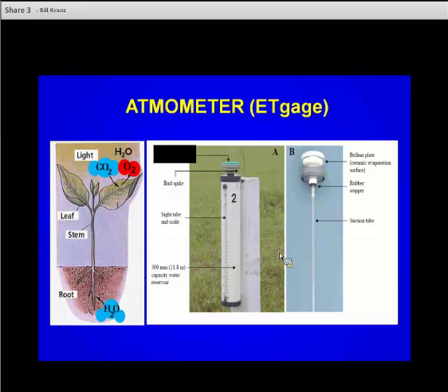Well, one thing is that when you pound a tube in, or a pipe in, well, a rod in, I guess I should say, you end up compacting the soils more around where this sensor is going to be than you would if you use a soil probe. And if you compact the soil, the water is not going to move in and out of the soil as you would like.